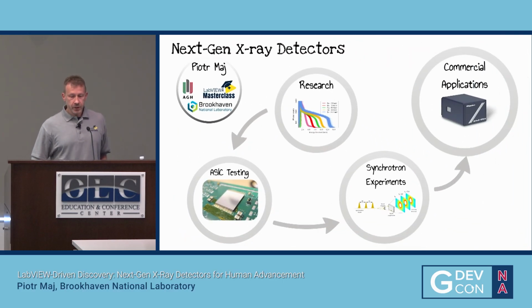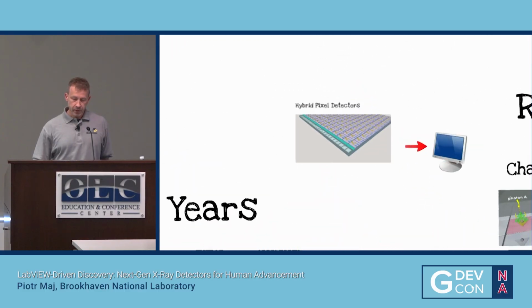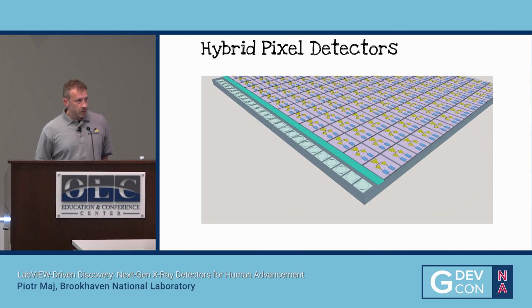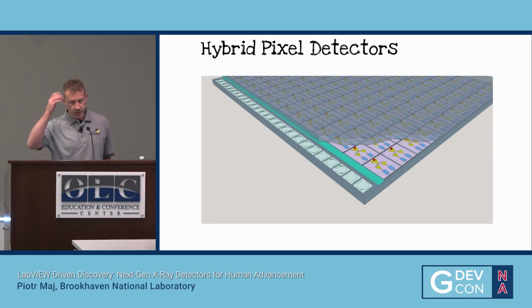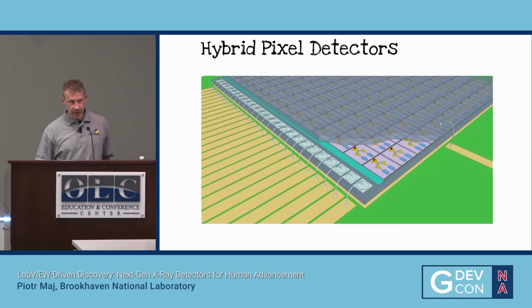My research goes around hybrid pixel detectors. Those are generally the same devices as you have in a phone, just with different photon energies. The X-ray energy is much higher, so the sensor is thicker and the pixel is bigger. Our pixels have a lot of functionality, not only a simple capacitor, but also an amplifier, shaper, and digital blocks. We connect those pixels to an external sensor, which is just a silicon plate. Then this hybrid structure we put on the PCB and connect with wires to have electrical exchange of